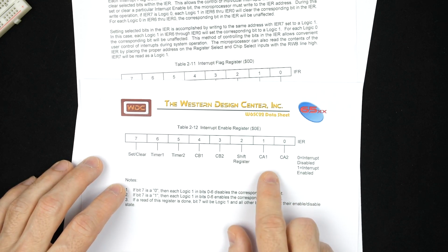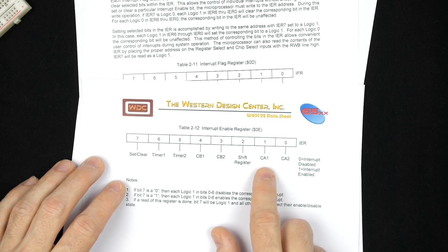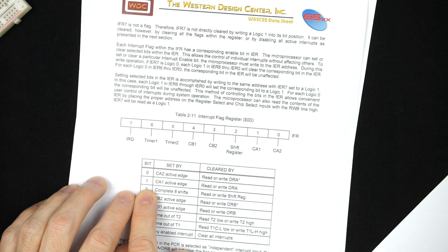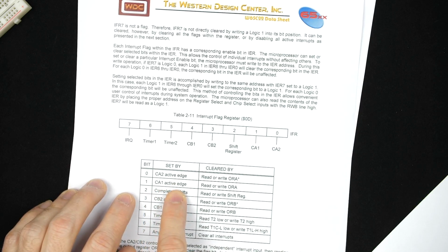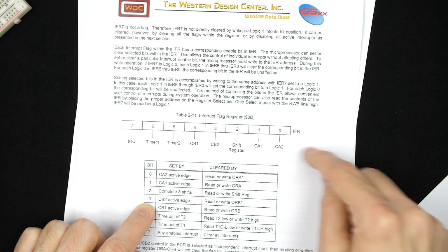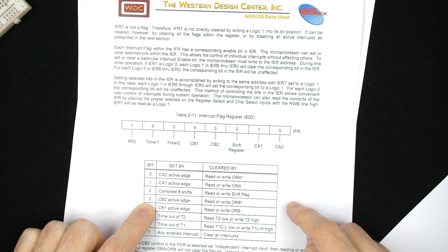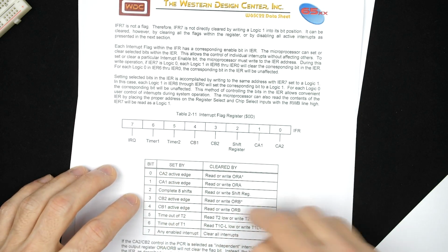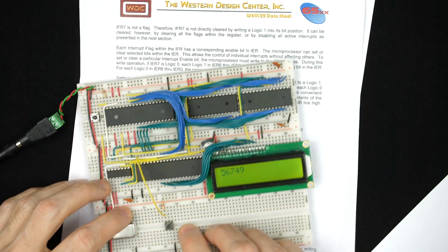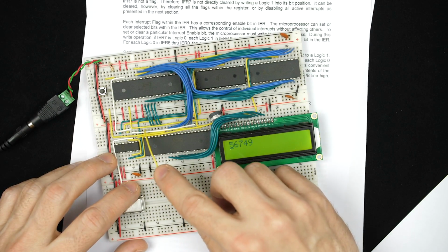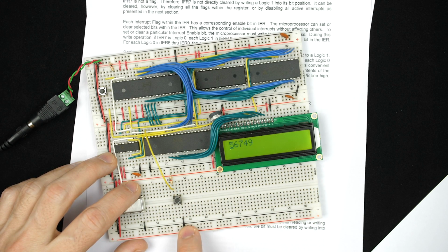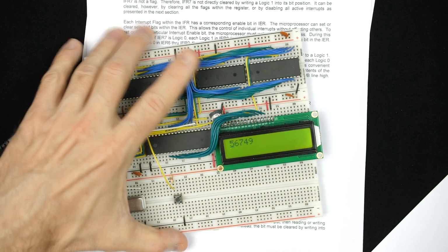Well, there is actually one other configuration thing that we can do, because CA1, what that says is that's going to activate an interrupt on a CA1 active edge. But it doesn't say whether that active edge is a transition from low to high or a transition from high to low. Both of those would be considered edges of a waveform or signal. And it doesn't actually say which one. And in our case, we want it to be a negative going edge, because right now this CA1 pin is tied high through this resistor. It's tied to 5 volts. And when we push the button, it'll connect it to ground. So pushing the button will transition it low.